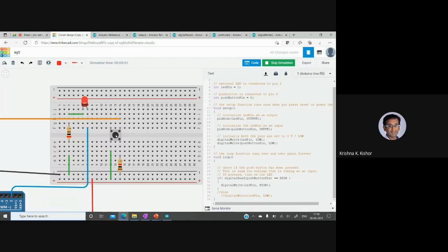So the switch is on, LED turns on, but I left the switch now, and the light is still on. Why is that? It's because from the point of view of this switch, the condition is only checking. Nothing is wrong syntactically. Everything in the code is correct, but your embedded system is not performing the way you want it to. So there's no syntax error in your code.